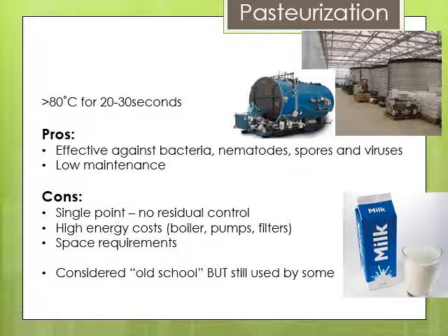Well, it's very, very effective against bacteria. Even nematodes, which are fairly large organisms, can be difficult to kill with some oxidizing agents because they're big, complex organisms. But here, viruses. So you can imagine veggie farms, some of them might still do this because of the very fact that viruses are impacted. Now UV lights will also kill viruses provided your flow rate is not too fast. We'll talk about that later.